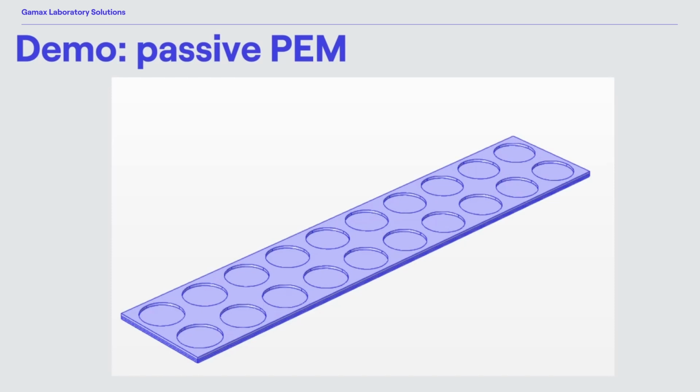But the hole to solid membrane ratio is maybe too large for structural rigidity, so we will use boundary layers to set up the diffusion layers. These gas diffusion electrodes are quite thin compared to the previous version, so we don't want to model volumetric mesh conditions. We will use surface boundary conditions with the same purpose.